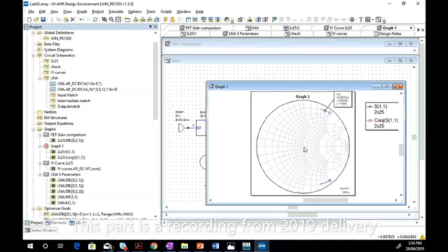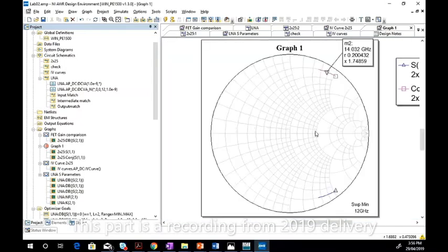So what you should do is you should probably have a few ways of doing that. You can follow a constant resistance circle, see this constant resistance circle, and then you can go up like that, right? Is that clear? I can't draw it here because it's AWR. If I follow a constant resistance circle this way, that means a series capacitor.